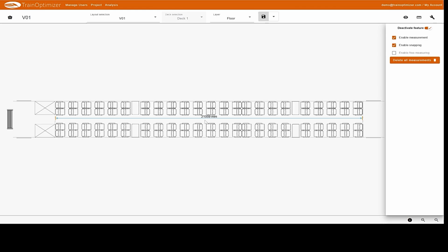In long-distance transport, on the other hand, where no standing room capacity is provided, the aisle element merely serves as a basis for the tool to recognize where and in which direction people move to get to their seats. This is relevant for calculating passenger changeover time. Now we draw an aisle with a length of 21 meters.